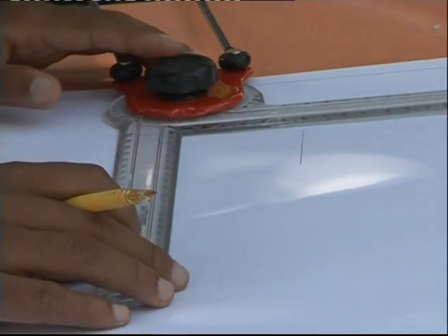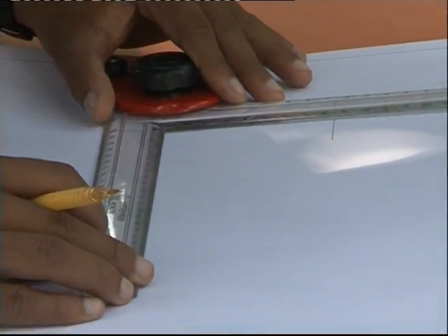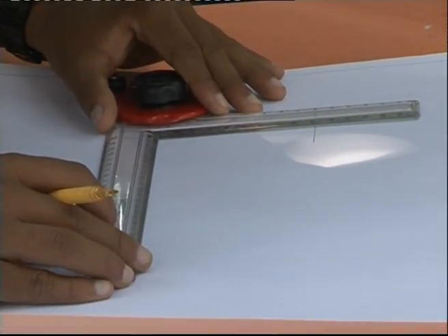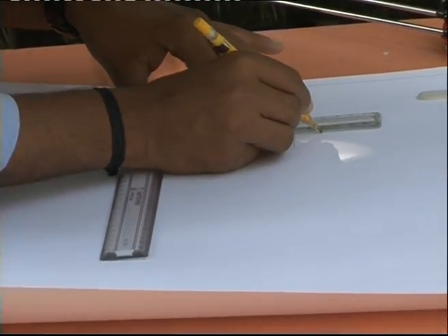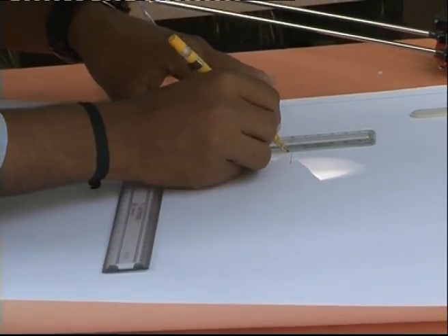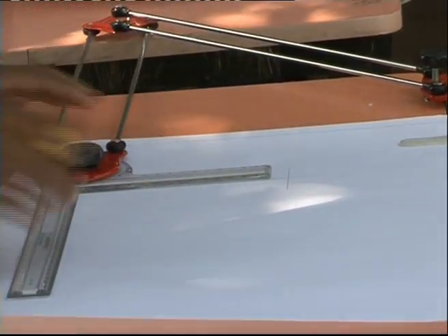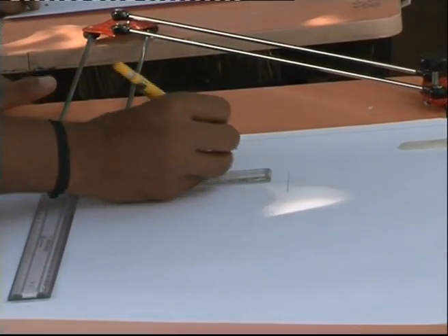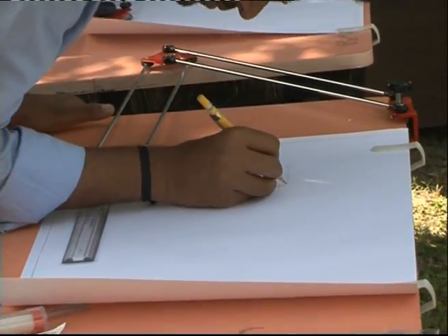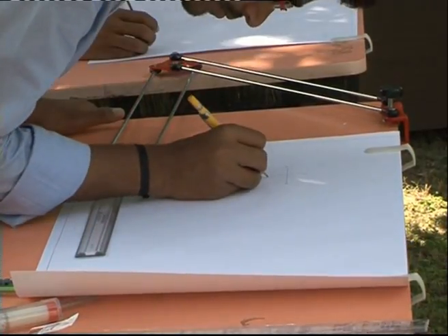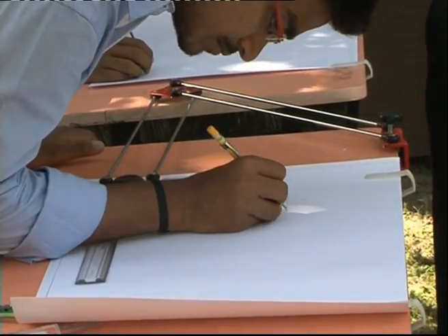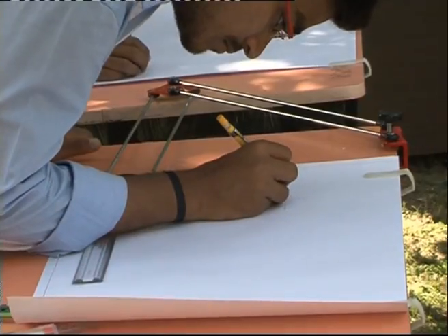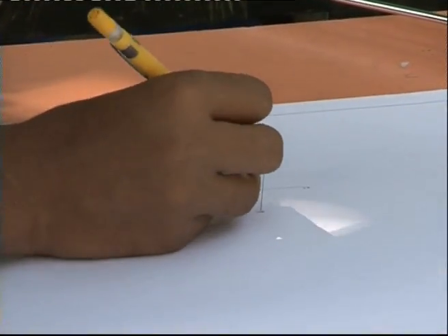Now once you have drawn it, you name it as AB. Once you have done that, the next step is to draw a minor axis that will be perpendicular to the major axis, passing through the center of the major axis, as I have shown you on the screen, and that can be depicted as CD. Okay, and the center can be marked as O.